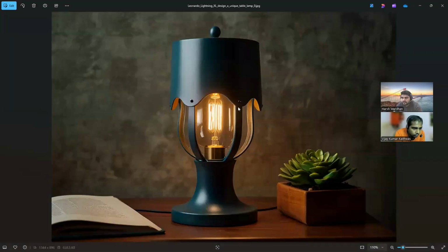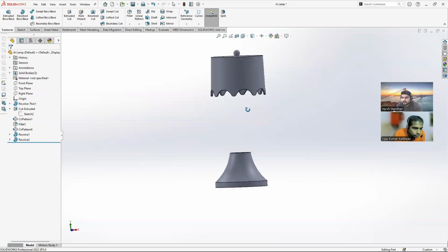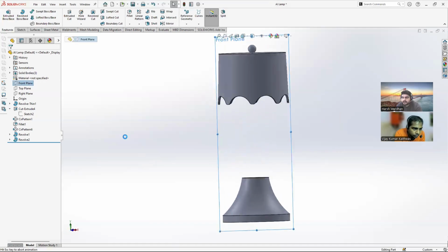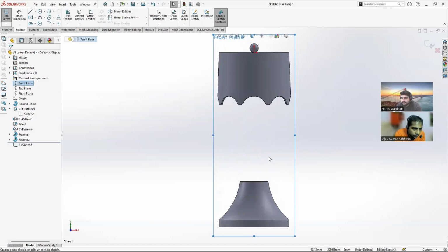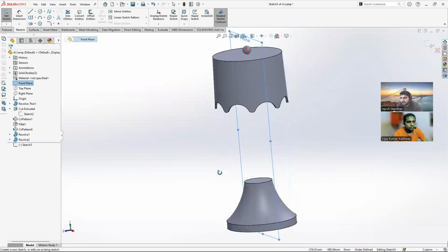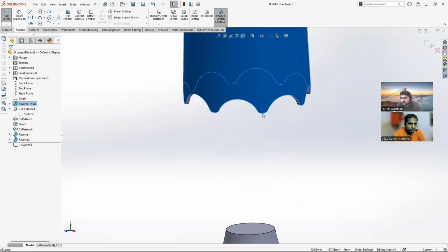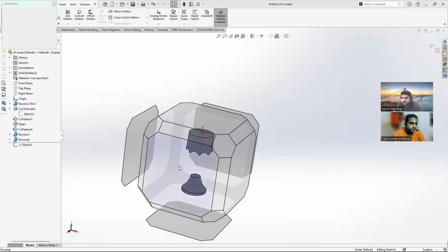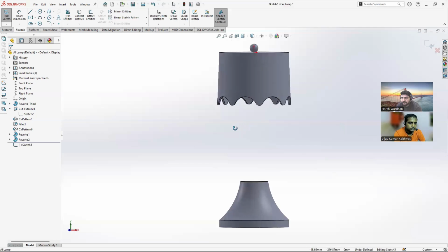Now we do these support strips. So I think we need 8 of these. So let's use the front plane again to sketch, or actually we need to join these projections. If we draw it in the front plane, that may not work.